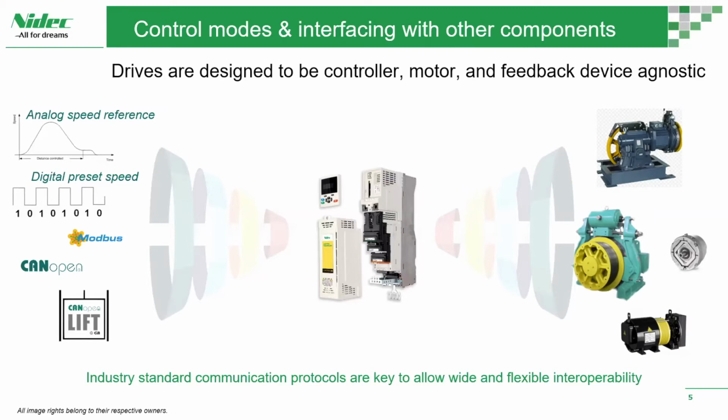But there's more control and more profiling basically done on the part of the drive. So the drive is no longer just a dumb device, but the drive and controller work in unison in delivering that optimum travel. And then coming on to the different protocols. So some of this can be realized through Modbus, CANopen, and obviously through CANopen Lift or CiA 417, which is just a very elegant and standard way of achieving all this.